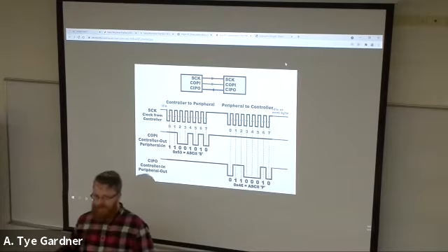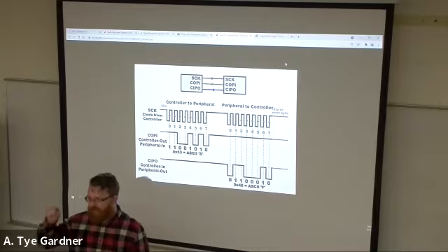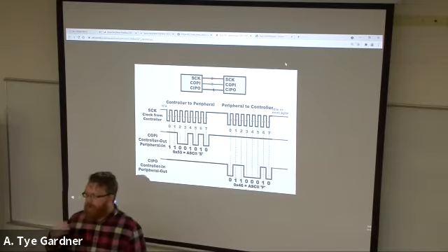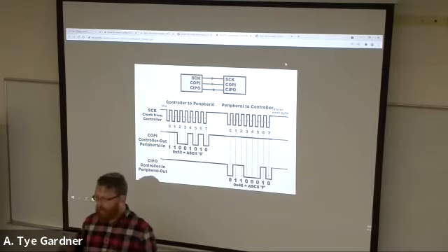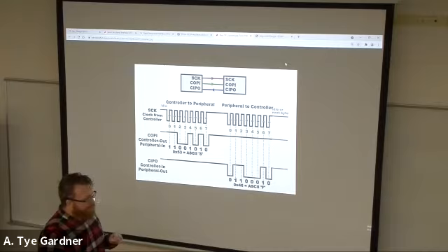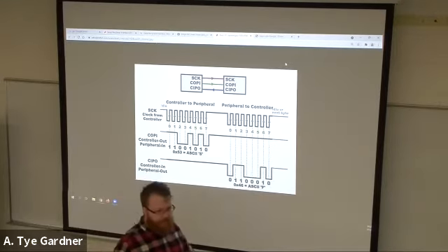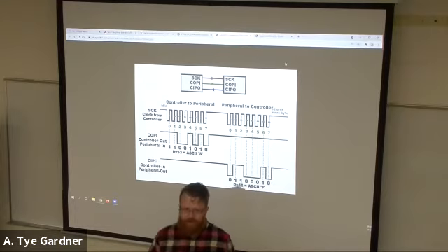Synchronous reset means that you only trigger a reset if there's a rising edge of the clock while reset is asserted. Asynchronous means that reset is in the sensitivity list, so it triggers regardless of the rising edge of the clock, right? The reset being synchronous or asynchronous does not define the communication protocol, it just defines your state machine. More specifically, the reset condition for your state machine.